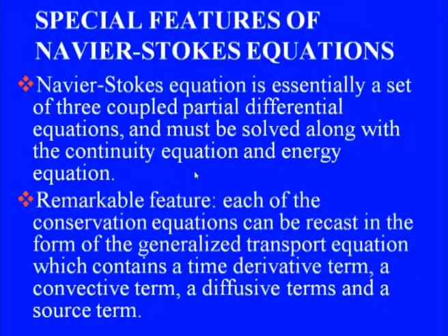Now yet another remarkable feature which we can observe is that each conservation equation can be recast in the form of generalized transport equation, which contains a time derivative term, a convective term, a diffusive term and a source term.